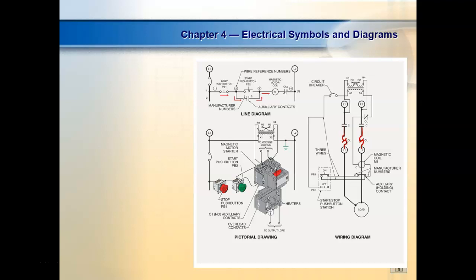So the problem with these electronic overloads, they got a little dial on them. You just take a screwdriver and turn them up, and eventually you'll turn them up and you'll burn up your motor, and then you're really down, right? So now instead of replacing a defective wire, you're replacing the motor.